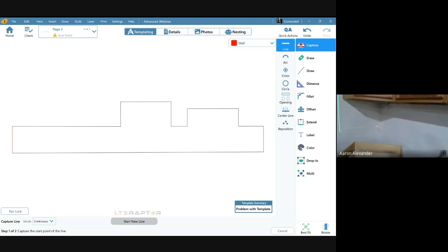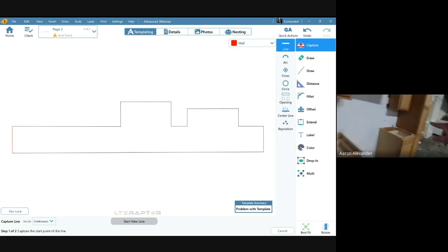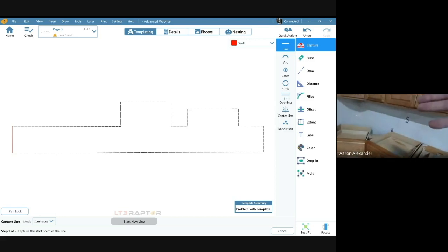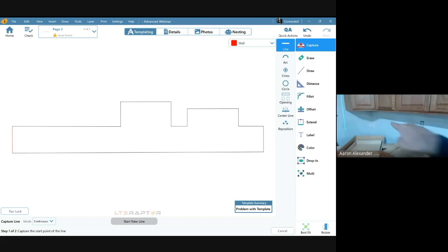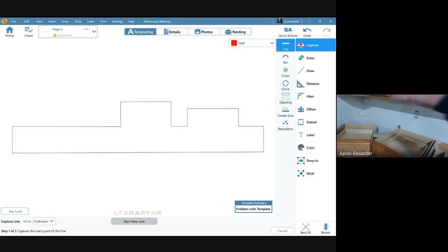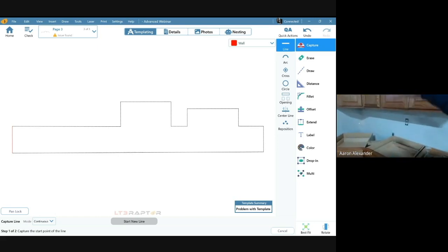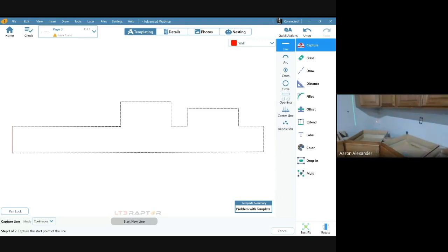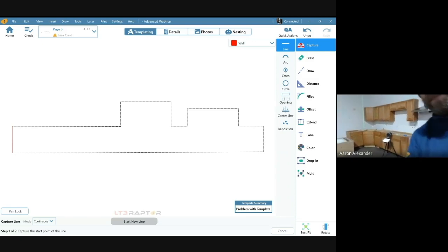If you come 3 inches out like this and you scribe up that wall that far out, I guarantee your back wall, the overall wall dimension, will be off probably 1/8 inch to 3/16, because when you go to check it, you're going to stick your tape measure into the corner right there, not 3 inches off the edge. So your tape measure is not going to match your laser because you're not exactly shooting what you're checking at the same time, if that makes sense there to you, Jimmy. Or to everybody, actually.